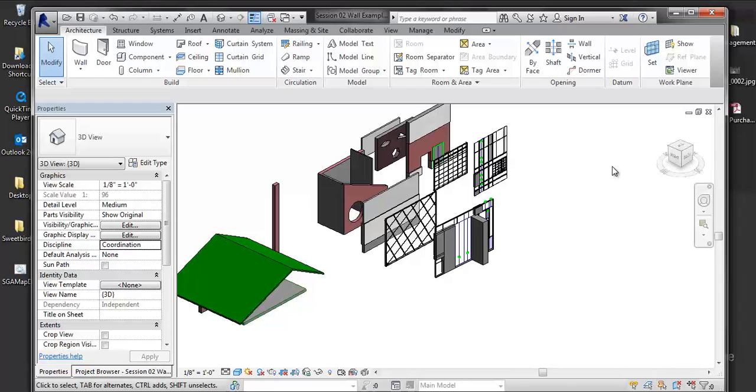I don't typically attach bottoms or tops of walls to geometry unless I have sloping conditions and profile conditions, because it adds a constraint to walls, and it's part of being an efficient modeler or efficient Revit user. File size gets big, as you'll see when you start to lock and constrain things. Oh, that's really fun, and now everything reacts off of that. Well, that adds processing time and save time. Again, it builds that little Swiss watch, where if you change one thing, then you break other systems.